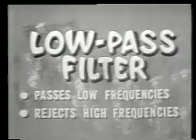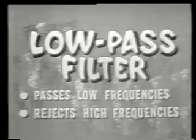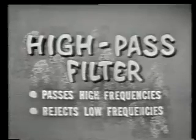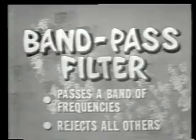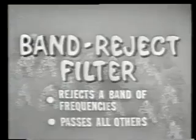Basically, filters are designed to do one of four jobs. One, to pass all frequencies below a specified value and reject all those above that value. Two, to pass all frequencies above a specified value and reject all those below that value. Three, to pass a selected band of frequencies while rejecting all others. And four, to reject a selected band of frequencies while passing all others.